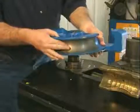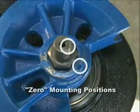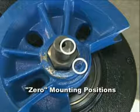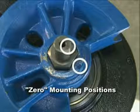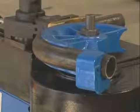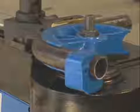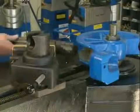And slide the center former over the hex shaft, aligning the 0 positions. For ease of use, all machine cases and tooling are clearly marked with 0 mounting positions. Tooling is machined to mount only at the 0 position of the hex shaft. Ercolina's patented swing-away counterbending die vise slides over the vise post and pivots, allowing quick loading and unloading of material.